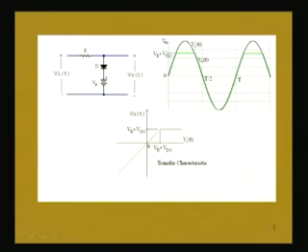So, on the straight line passing through this origin, the voltage input and output will be same, and it will be continuing till the point when Vi is greater than Vb plus Vd naught. So, when Vi is greater than Vb plus Vd naught, the voltage is constant at Vb plus Vd naught. So, that is why it will be constant, and whenever Vi is less than Vb plus Vd naught, it will be bearing a linear relation with slope 1,